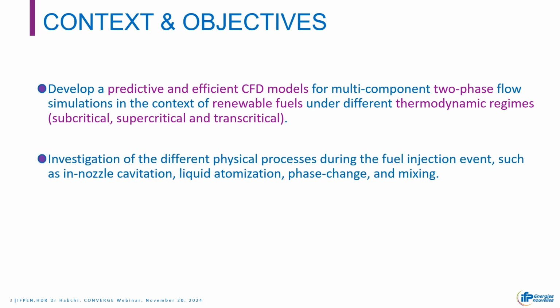The second objective is the investigation of the different physical processes during the fuel injection event, such as in-nozzle cavitation, liquid atomization, phase change, and mixing.